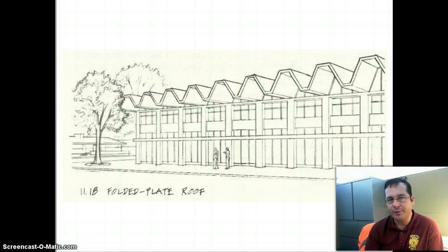This is called a folded plate roof, and you've probably seen this many times before in many different demonstrations. Local examples of this type of roof would be the Alliant Energy Center. The Coliseum itself actually has this kind of corrugated folded roof, which produces greater strength than if it were a simple dome. Of course, the other application, the consumer product application of this, is in the use of cardboard. If you think about why this works, what we've been able to do is take this thin sheet and push the extreme fibers further apart.